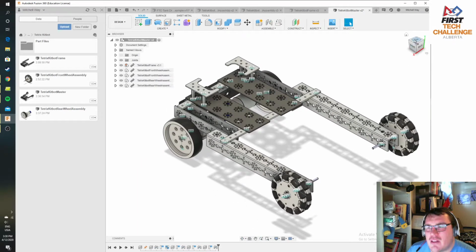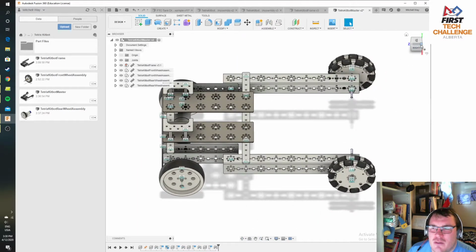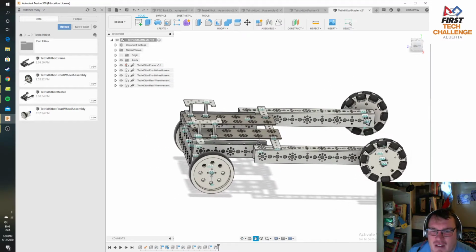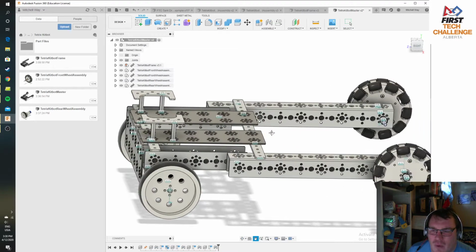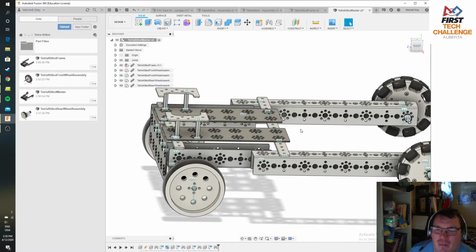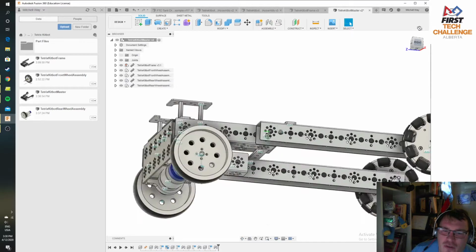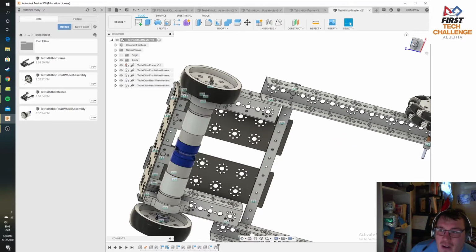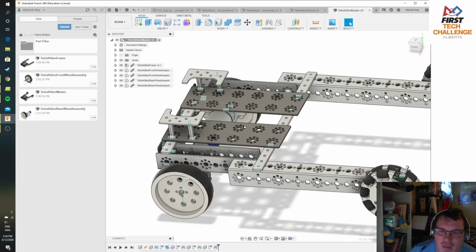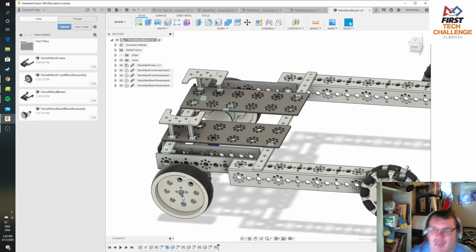The other thing you're going to realize on this robot in particular, and I've seen a few teams use this particular chassis almost as is, you have to consider where all the weight is on your robot. And right now we have a bit of a problem. The biggest problem being that the battery holder's back here, that the two DC motors are back here. All of the heavy parts are sitting right over top of those rear wheels. So this robot, when it drives forward, is going to tend to pull a wheelie. It's going to tend to have its wheels fly up in the air. And you kind of have to keep that in mind when you're designing, which is going to lead us to our next design in just a second.